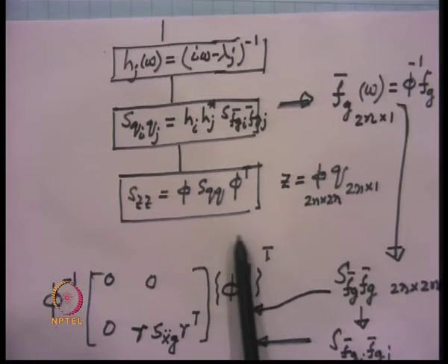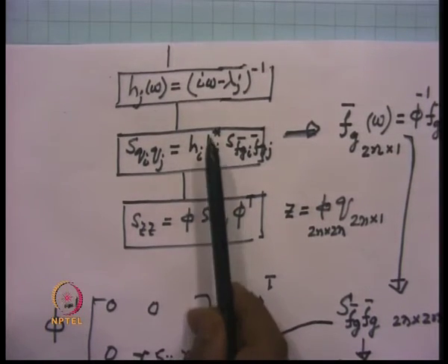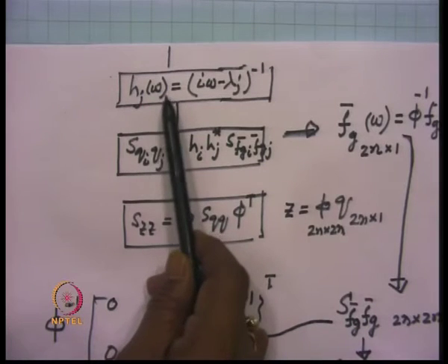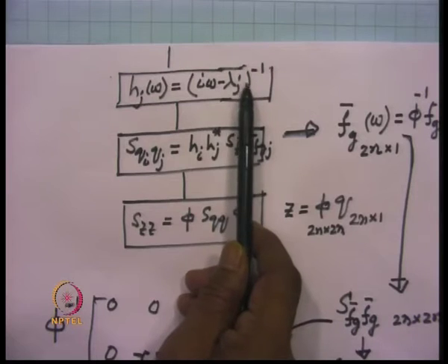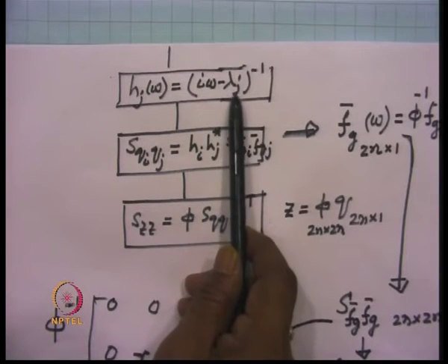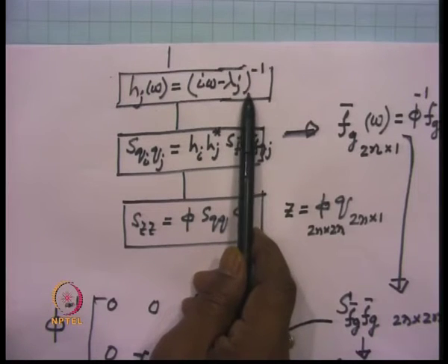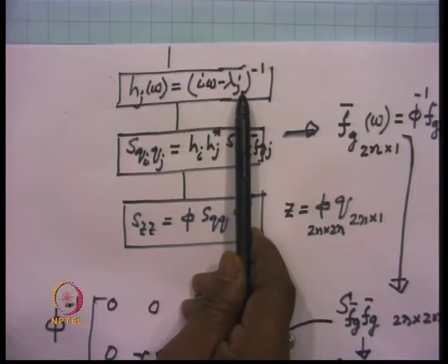If you are wanting to use the modal state space analysis in the spectral analysis, then we obtain for each mode the complex frequency response function, and this will require the knowledge of the eigenvalue of the particular mode. This eigenvalue is generally a complex quantity.